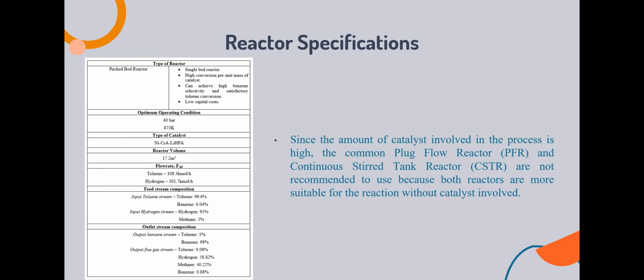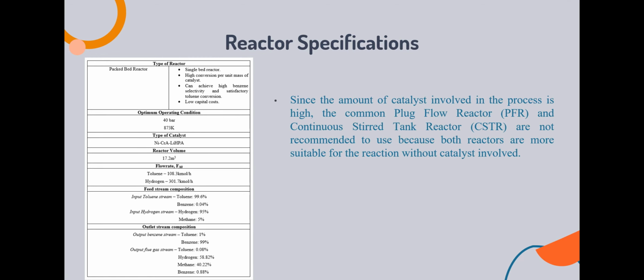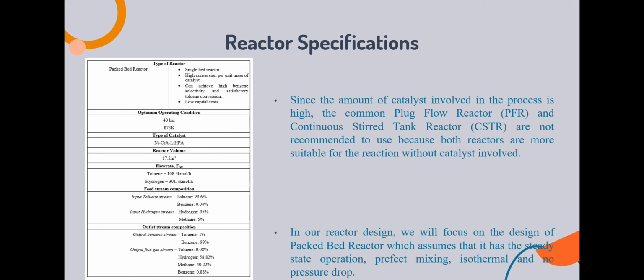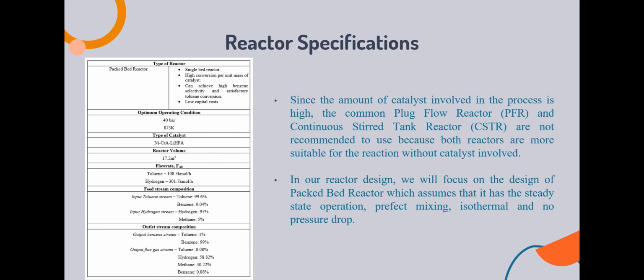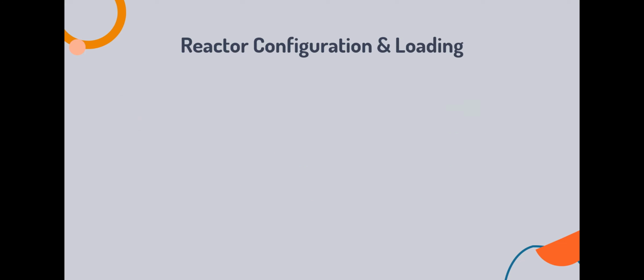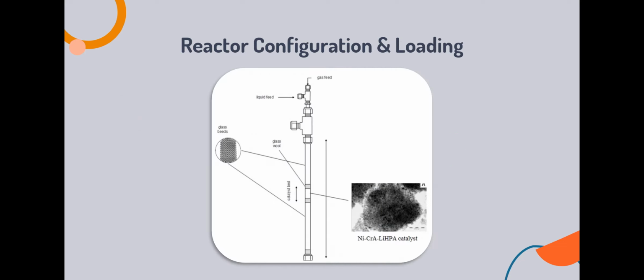And since the amount of catalyst involved in the process is high, the common plug flow reactor or PFR as well as the continuous stirred tank reactors CSTR are not recommended because both reactors are more suitable for reactions without catalyst involved. In our reactor design, we will focus on the design of packed bed reactor, which assumes that it has a steady state operation, perfect mixing, isothermal, and no pressure drop. Reactor configuration and loading is shown based on this diagram on screen.